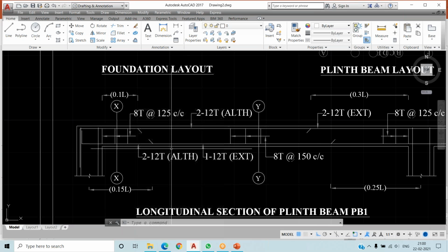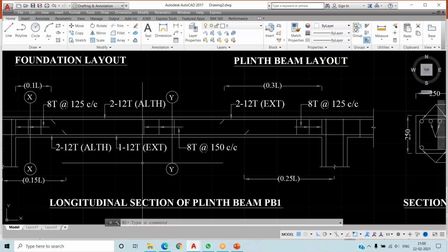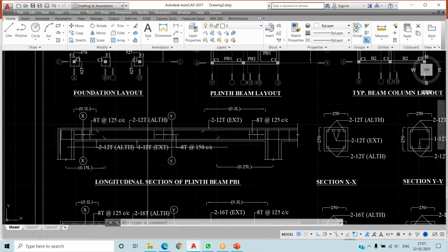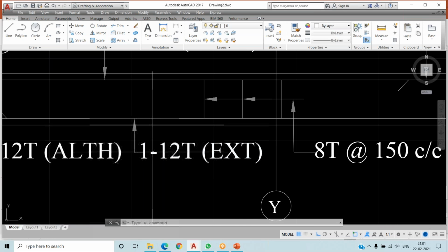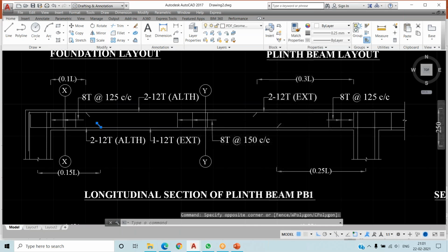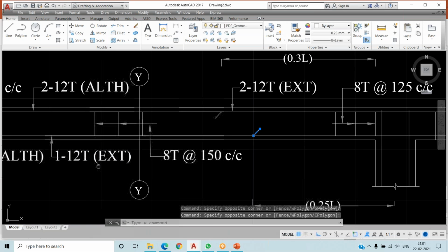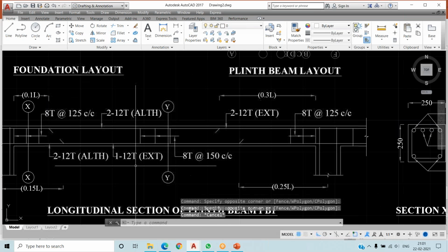Okay. Now we are going to give the extra reinforcement bar according to design criteria over here. That is 12 mm dia. We are going to provide extra reinforcement. How you are going to identify this is your extra reinforcement? You have to just make a line like this to show that it is the extra reinforcement. It is the section view of the beam.